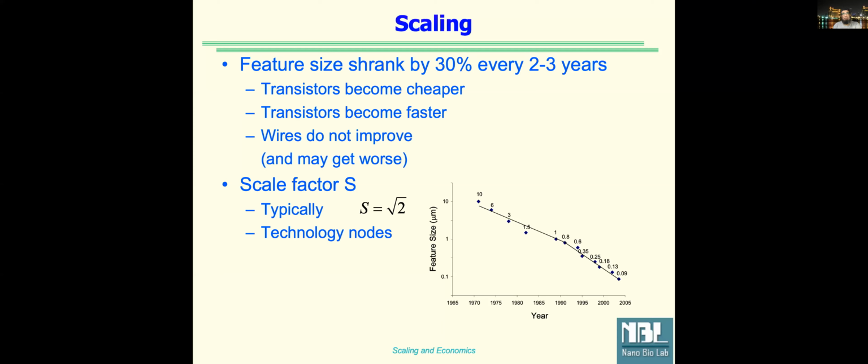They became cheaper, they became faster, but new issues started coming up, which was about how do you connect them? How do you wire them? How small do you make that insulator that doesn't let any electrons pass through it? But we became so small that now the electrons would tunnel through that. So we had to change materials. Instead of silicon, we have started using hafnium dioxide, for example, in those spaces.